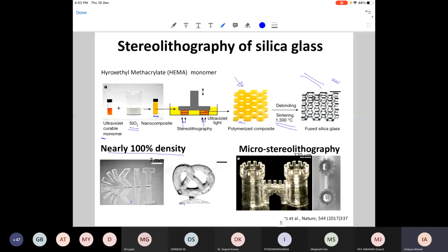Generally, rheology of the paste plays a very important role. The reason is it requires thixotropy. That means when you apply the load, the slurry should shear itself, should readily shear. At the same time, when you remove the load, that means when it's extruded out and deposited, it should stand on its own.